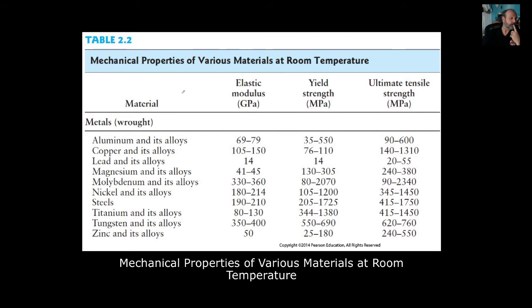That's something to remember. Okay, so for some applications you want a stiff material, and for others you want it more ductile, more flexible, more bendable, a lower Young's modulus or elastic modulus. Okay, and that's in pressure units, gigapascals, so you can see you have a wide range of stiffness.